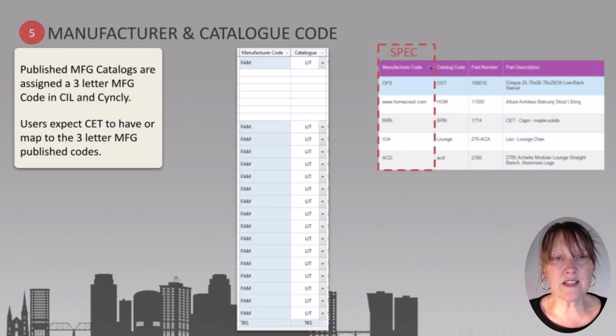For existing extensions in the marketplace that do not have the correct manufacturer code, your development partner will help you fix this. It is not just going into your catalog creator and updating that URL. We have to consider previously drawn symbols that are assigned to the old manufacturer code. Those old symbols are not going to map to the new code, resulting in white boxes or UFOs in the drawing. So please work with your development partner and ensure that it is going to map over into the next specification tool and that your existing symbols do not get disconnected due to some of those big changes that take place.